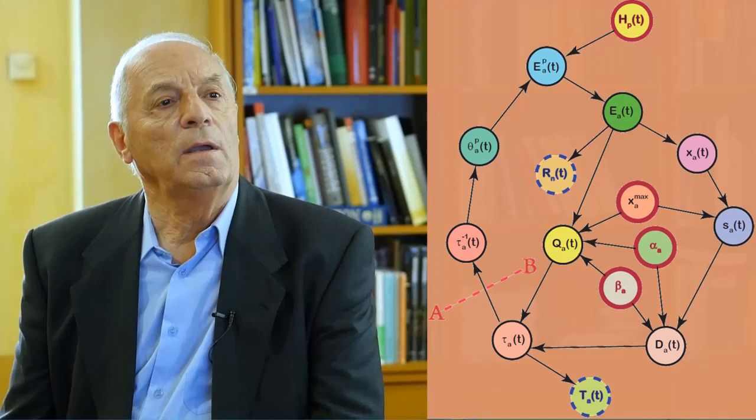All the above shows that we can use initial spline functions for the functions tau A of t, for example, calculating the free flow link exit time functions, and use an iterative method in which we use in sequence all the equations to calculate the same function tau A of t and repeat the process until convergence. This is what we have done in our MATLAB program.